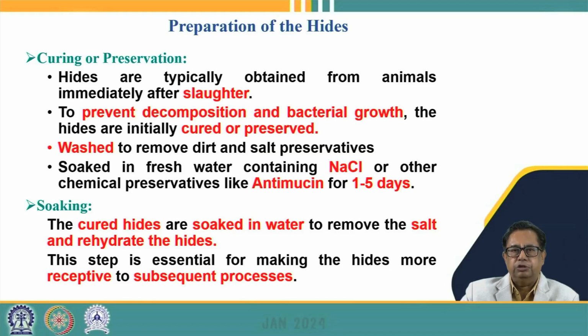After the curing process, we go for soaking, where the cured hides which have been soaked in salt water or in preservative water are now soaked in water. The salt that we have used may have dried the leather. So to rehydrate the hides, we generally go for the soaking process, where it is soaked in water for a long time so that it becomes receptive to the subsequent processes.